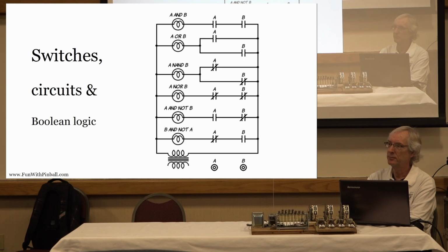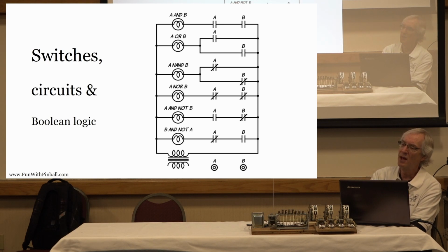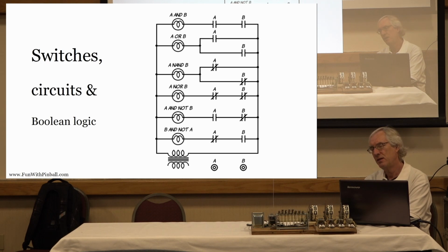The end of stroke switches, they had those real short end of stroke switches that broke off because they were getting so much flexation on a short blade. What else? The end of stroke switches were really a big trouble spot for a long time.